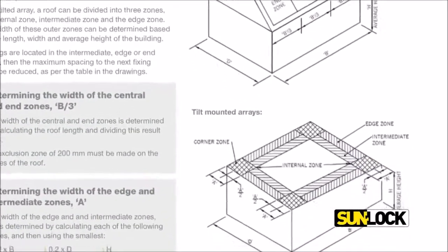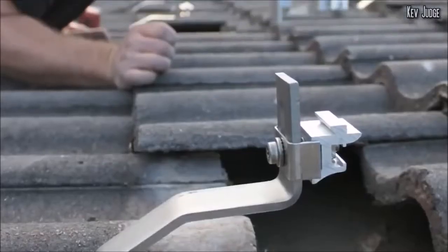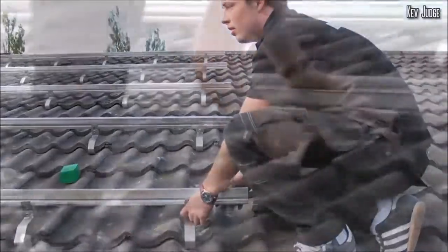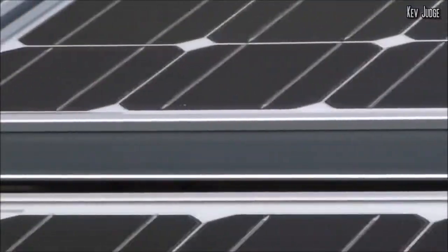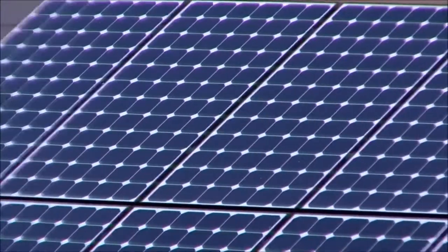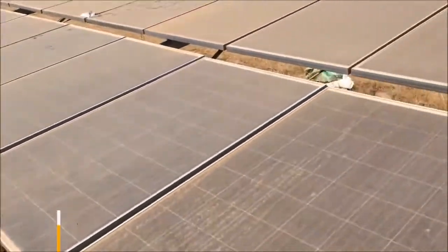For a new house, the design of the mounting structure with the solar panels must include a static evaluation of the roof. For existing homes, the service of a professional structural engineer is required in order to carry out an inspection of the roof structure and do a calculation of the structural loading capacity.